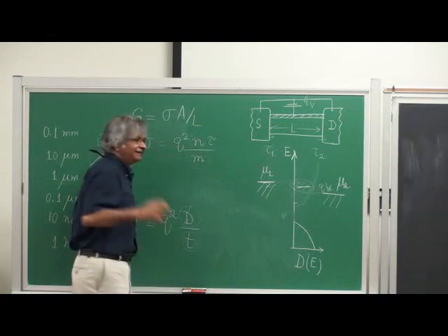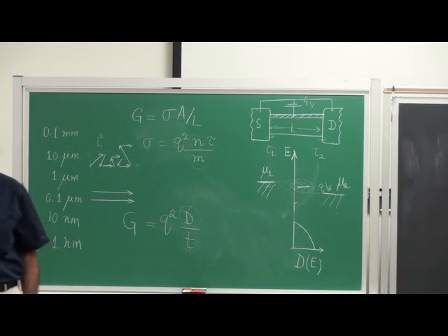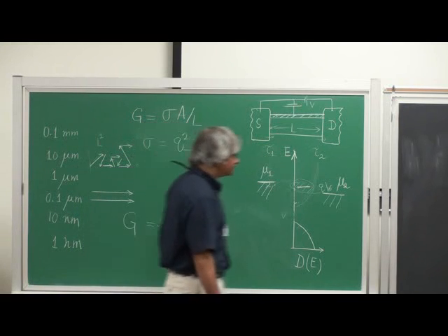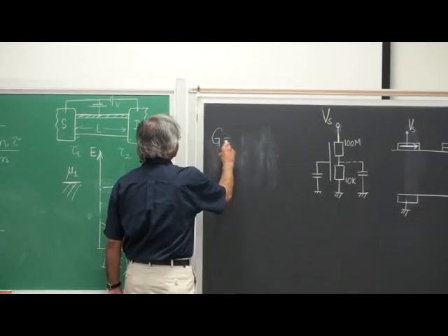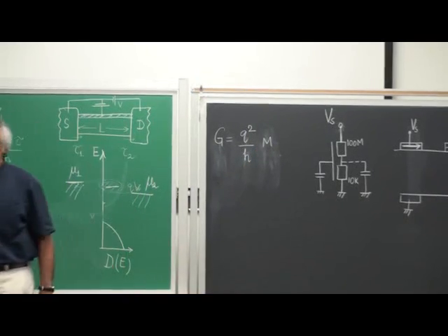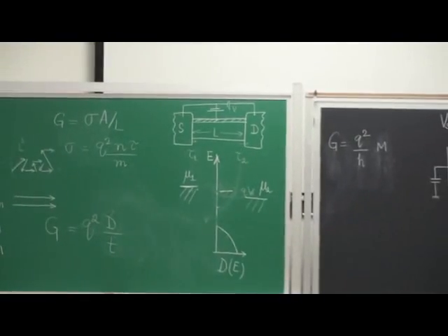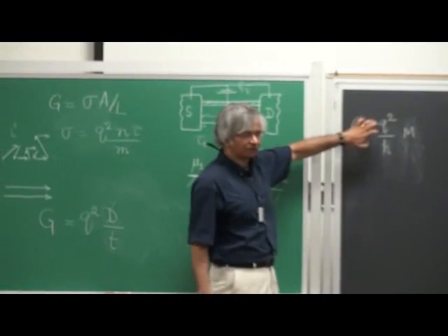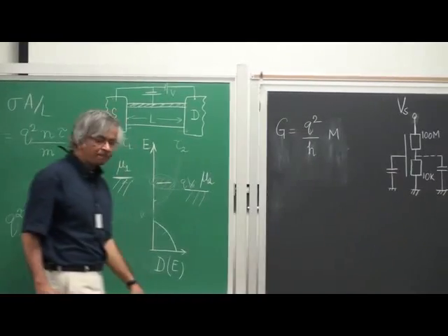one important quantum input into this that I want to bring in that was unknown, was not appreciated, say, before 1988. Because in 1988, there were these two groups who reported an experiment measuring the conductance of ballistic conductors, something that was really small. And what they found is that the conductance of something really small could be written as q squared over h times an integer. That's what was experimentally shown. And that is one of the most important advances in our field. I'd say one of the most important experiments. That's about 20 years old now.